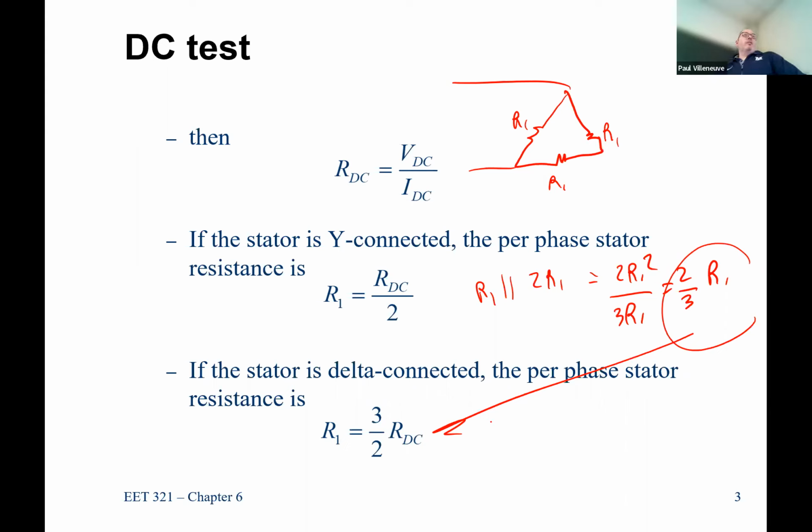When you buy a motor, if it's a decent sized motor, say 50, 100 horsepower, those are fairly common. You can order them from Baldor or Reliance and you can get them a dime a dozen. So they might not have a factory acceptance test result, but if you're buying a custom application, where it's a big motor or it has some different characteristics, you might actually put it through its paces to get some real test data.